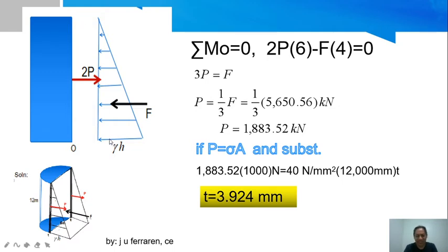So this time, you are only given the option on what thickness you are going to use. But for now, just limit your approach. And the formula we are using for cylinder, pd over 2t and pd over 4t for